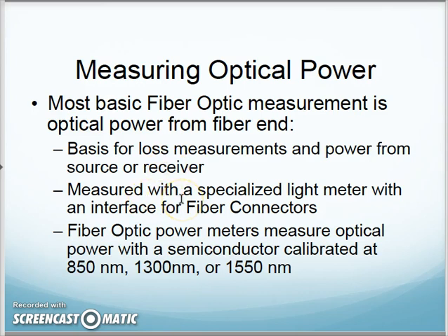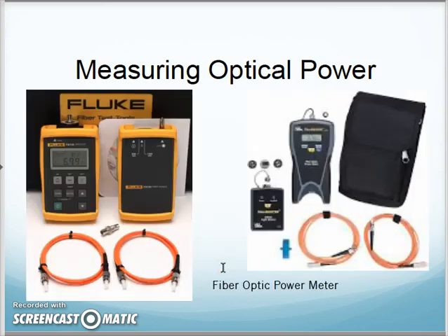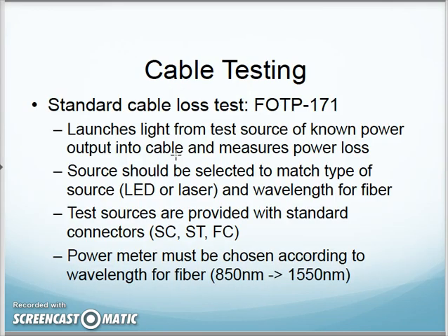Measured with a specialized light meter, yep, your fiber optic power meter. It actually has interfaces for the fiber connectors, and it typically measures at 850, 1300, and 1550, your multi-mode and then your single mode light sources, if you will. And again, here's your fiber optic power meter. It's two different examples, so you can just kind of visualize what you're seeing there.